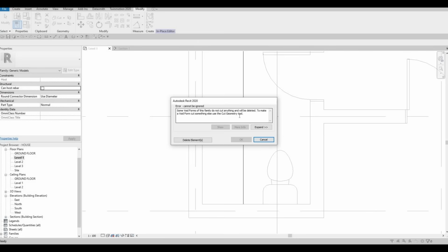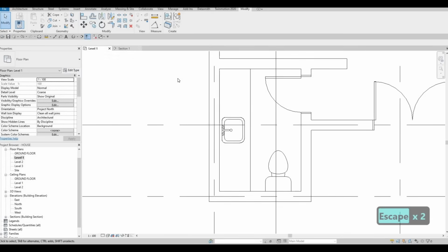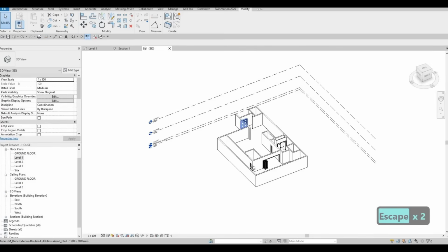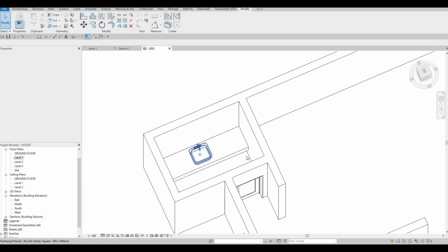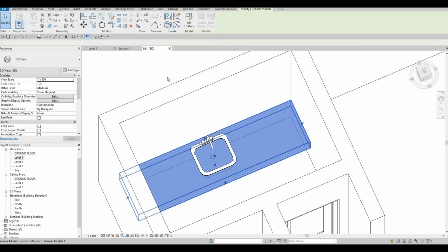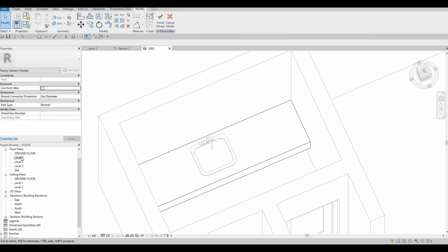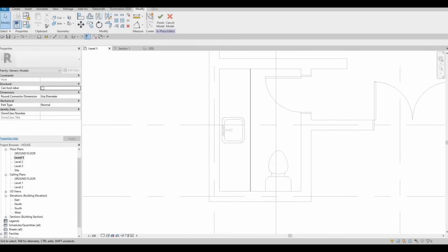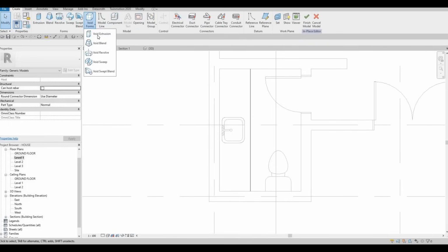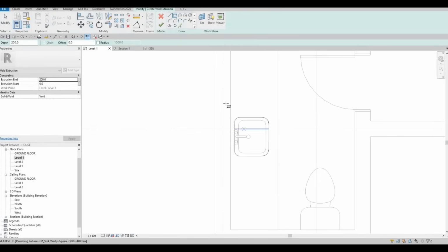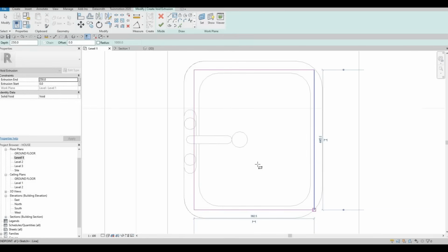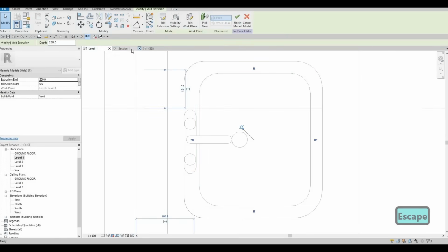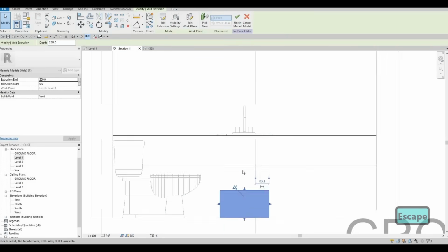The void form of the file, do not cut anything, will be deleted, because the way this one works is we need an opening for that. I'm going to show you guys because it's not visible, it's just like that. So I need to do this again. I'm going to click on void extrusion again, make sure everything is cut accordingly like that. Click on finish, do the section again.